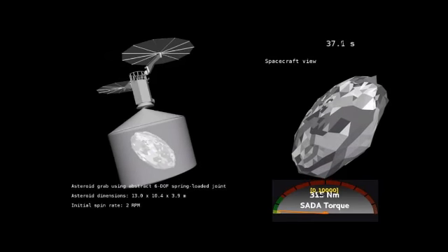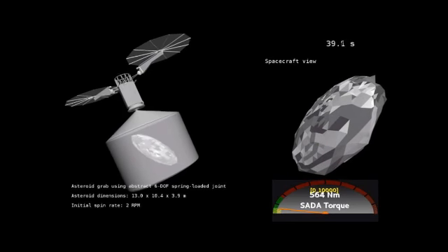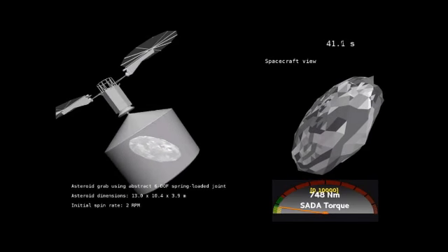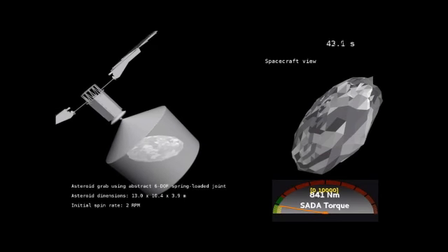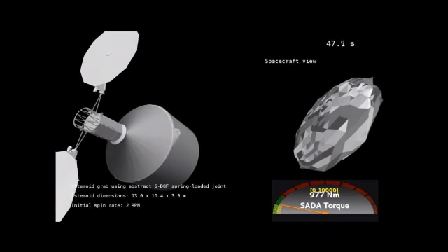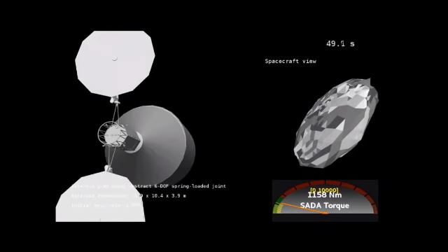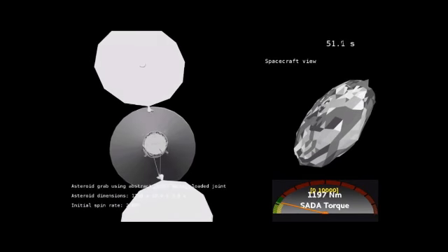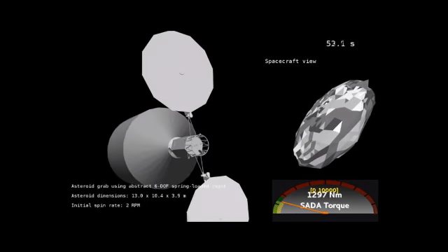Now you see that the spacecraft starts to accelerate promptly to follow the motion. There's almost no relative motion from that point. You want a fairly stiff system in order to achieve that, and we believe that with appropriate fabric shear panels within the airbags, we can get the stiffness we need.